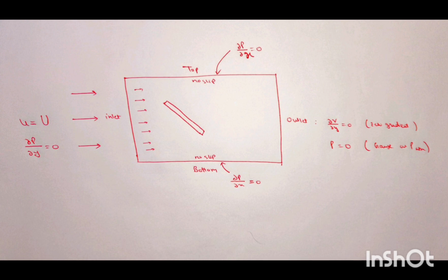Also we have taken the thin rectangular sheet as a solid wall, which means zero pressure gradient and no slip condition. We have done simulation on two different types of mesh, but we did our analysis on the same one I explained above.